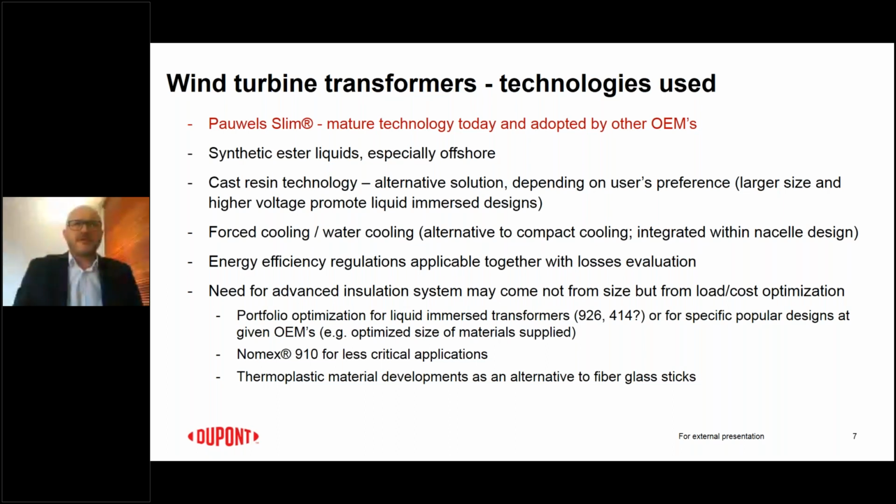Over the years, there was also forced cooling developed for the step-up wind turbine transformers, especially when we have transformers installed in the nacelle, where there is a cooling needed for the generator, for the inverter, for the gearbox. Many wind turbines basically have the integrated cooling system for all the components to be pulled together with one system, which includes the water cooling, and then water cooling also is used for the step-up transformer, and then the size of the cooling system for the transformer itself is not so critical because the cooling system is installed for all the equipment.